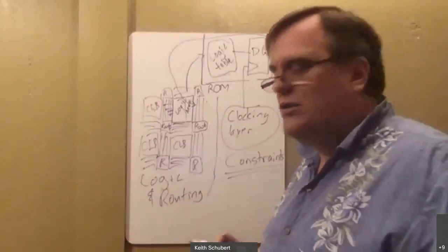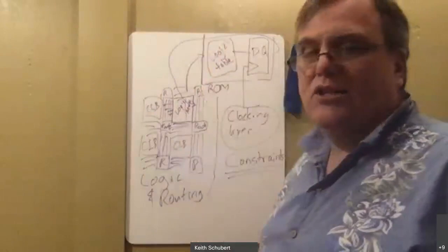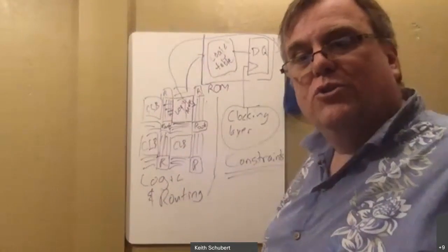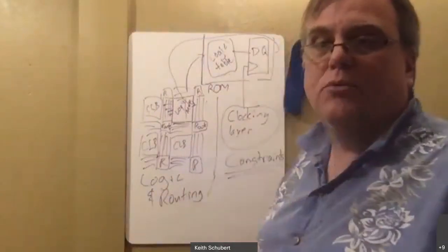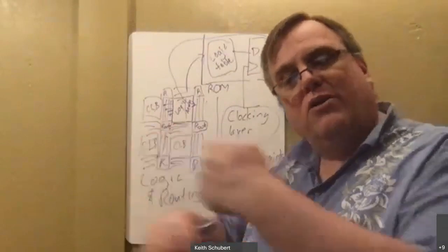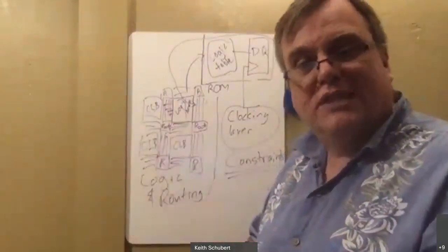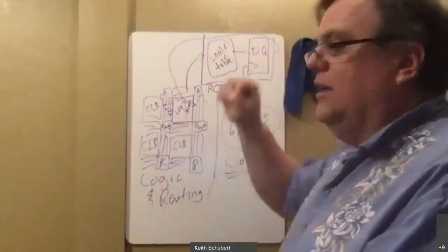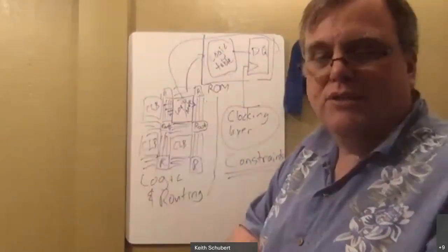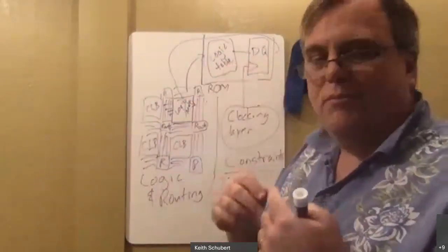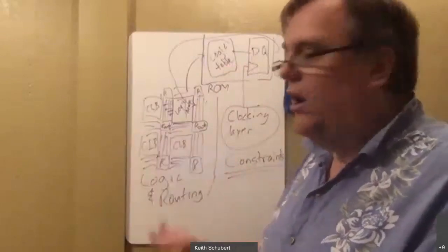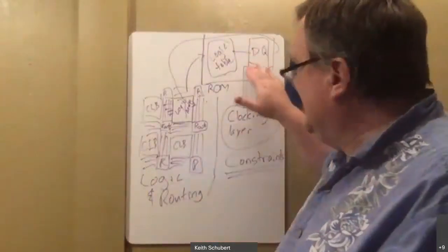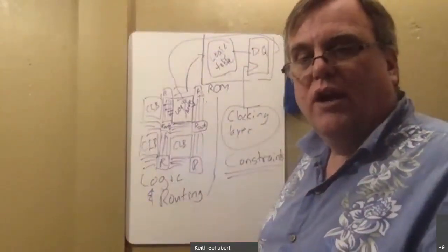Once the timing constraints get into problems like that and you're feeding logic back into logic without being able to properly use this, what you'll get stored in these locations will be intermediary results. Remember how it could take a couple times till the flip-flop settled its value? Well, that means in the meantime, it could be turning on and off. You've missed the things, so it can become metastable. You can get errors of type 1. All the protections that are normally here get blown away because that's not what's supposed to be used, right?